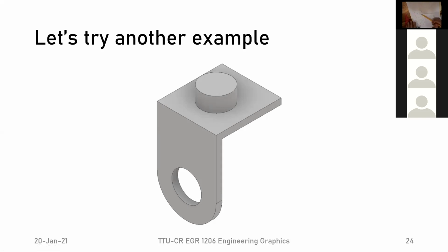So if we're looking at this without knowing the three-dimensional thing, then we know that there's something going on in this area. All right, so these were the hidden lines. I think that's all the hidden lines that we need to do. And after that, we can now go and do our right side view. And now, just as a different example, we'll do it without that diagonal construction line, just so that you see both ways.